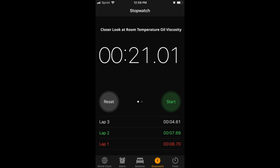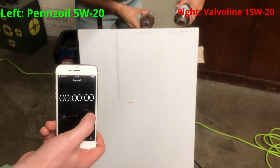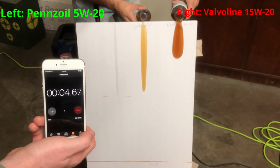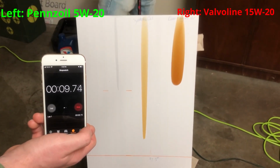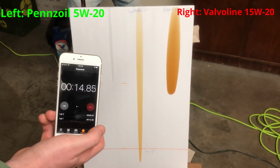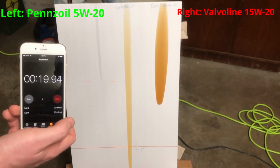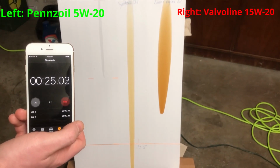Our initial room temperature run had synthetic oil flowing across the board easier than the diesel engine oil, leading us to conclude that synthetic oil is less viscous than the diesel engine oil, probably because it is a little thinner to account for smaller clearances in the smaller engine sizes. For our second run, we took the same amount of synthetic and diesel engine oil and stored it in a deep freeze that was set at around 0 degrees Fahrenheit. So the synthetic oil again ran smoothly across the board, while the diesel engine oil seemed to have thickened up, and this flowed a lot slower than the room temperature run.